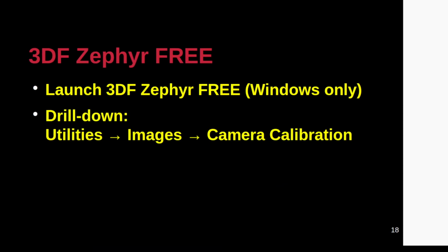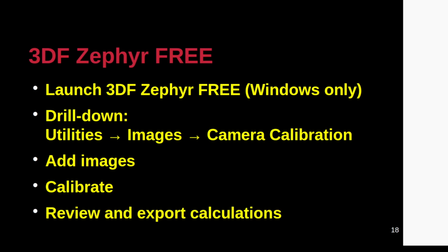Launch 3DF Zephyr Free. Drill down from the main menu bar, select the Add Images button. Use the file dialog box to open the image files. Perform the calibration. Note the estimated calibration values and export the values for use in FTC projects.